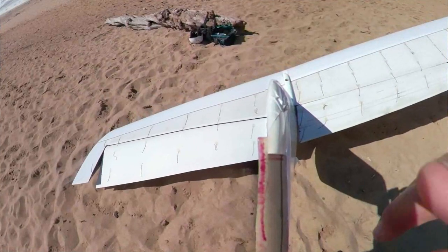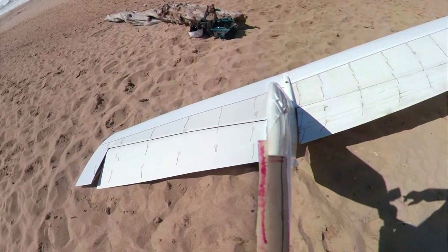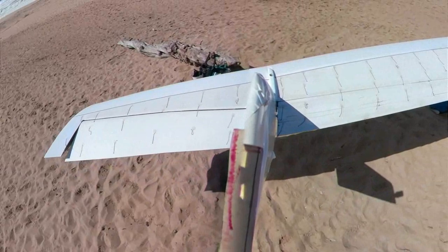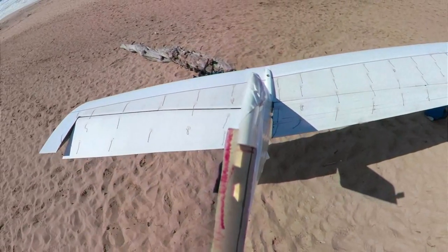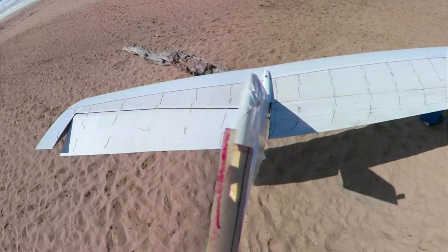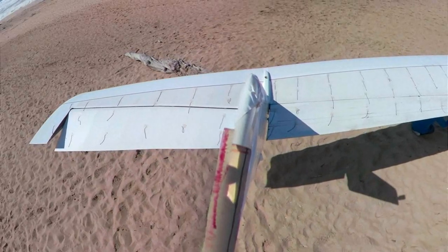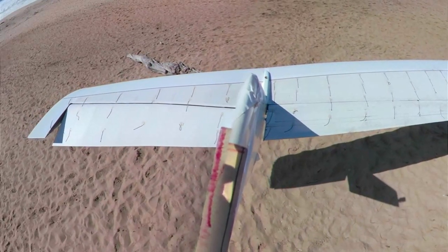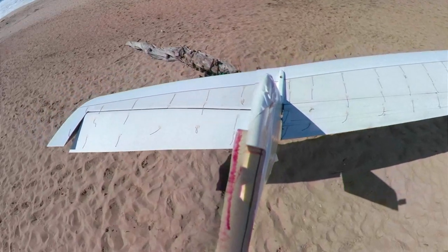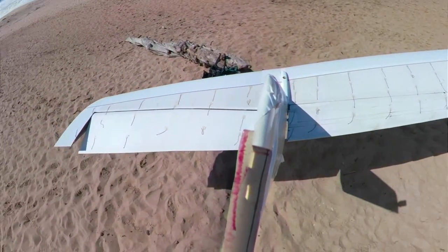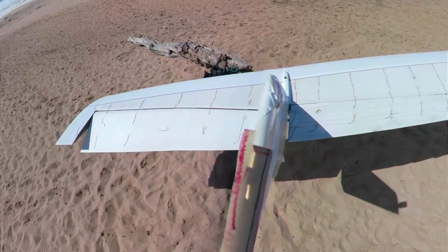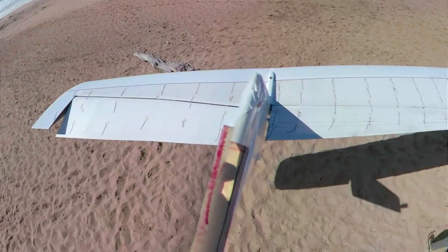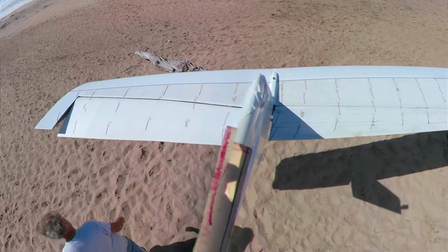So here we are, a couple of months later. As you can see, I've cut the elevon out of the wingtip panel, and I just followed the same hinge line as the inboard elevon, and that took the hinge line very close to the spar. I wanted to do that on purpose because if you watched the earlier videos, you know that I did some tests that showed if you do this, you're picking up the flow that has more energy in it near the maximum thickness point, and the flow stays attached better to the elevon.